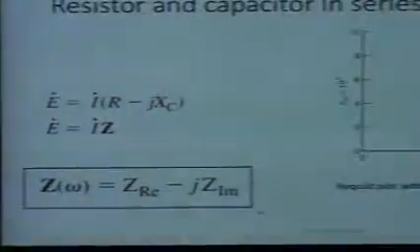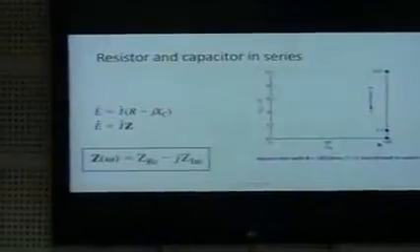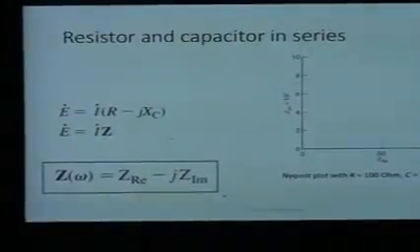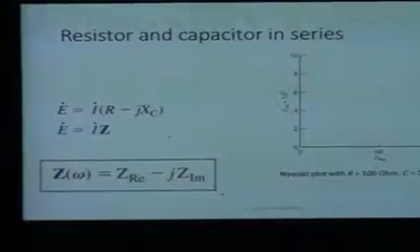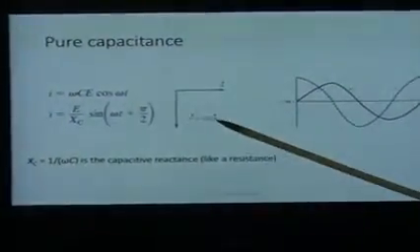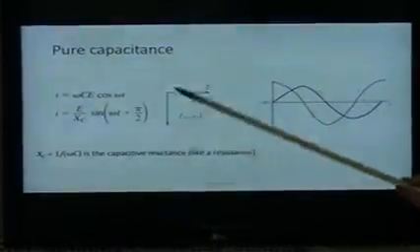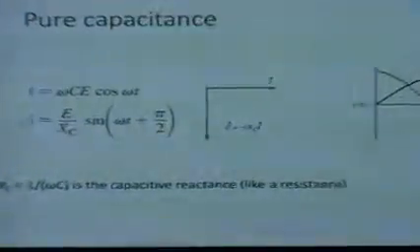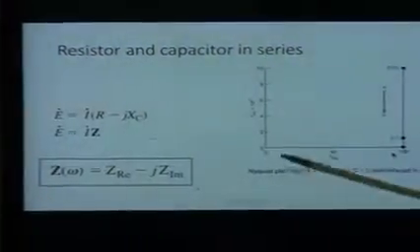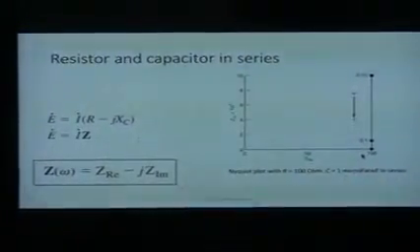And I will note that in the development that we're showing here, we're using a minus sign on the reactance component. Not all of the textbooks will do that. Sometimes they'll use a positive sign, just, I guess, to avoid confusion, in which case everything is just sort of flipped. But the reason that the negative sign is used here is that the current is phase lagged by 90 degrees behind the electric field, and so it's easier to imagine in your Nyquist plot. Your imaginary component through this definition is always positive. Okay, so that's why it's done.